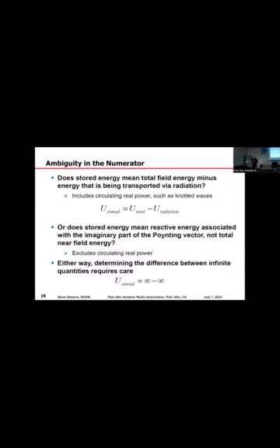It has zero divergence. So the Poynting vector forms a closed loop on itself, and the energy just goes in a circle, like an electronic flywheel. But it's real power. It's not imaginary power. It's not reactive power. It's real power that's just going nowhere. So do you include that power in the numerator or the denominator of this calculation?